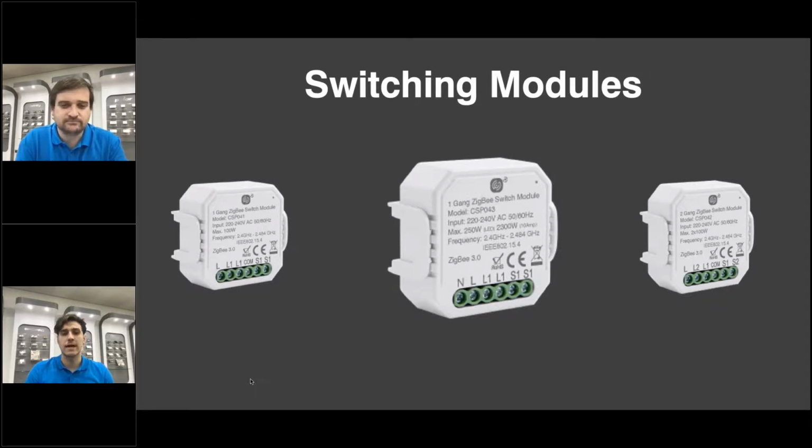And again, it just needs that. However, the other ones to the left of it, I'm just trying to see because my bar's in the way. To the right of it, that doesn't require a neutral. So actually, when we spoke earlier about these devices and using them to get us out of sticky situations where we can't get wires there, or there's a problem, sometimes there may not be a neutral at a lighting point or a light switch. Therefore, you can actually fit these without a neutral, which is again an added benefit of these devices. I remember when I first started my apprenticeship, Jake, if I ever suggested taking a neutral to a switch, I think I'd have been flogged.